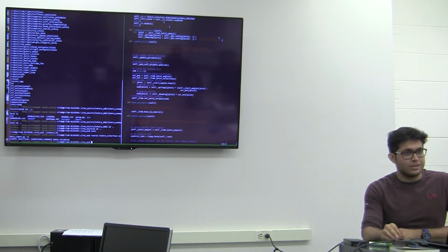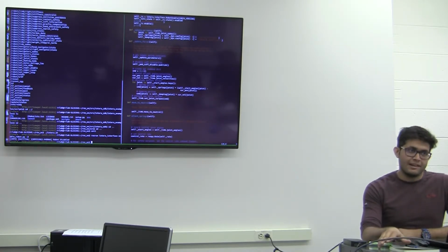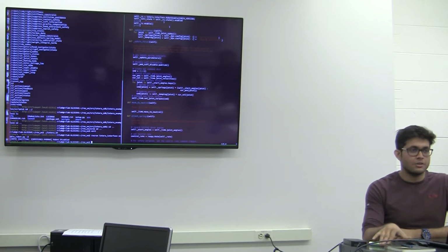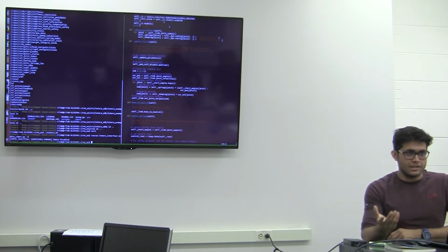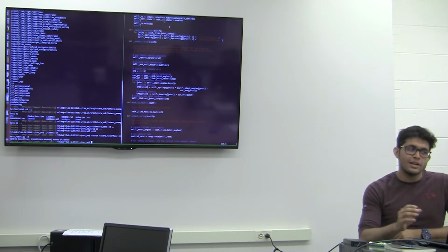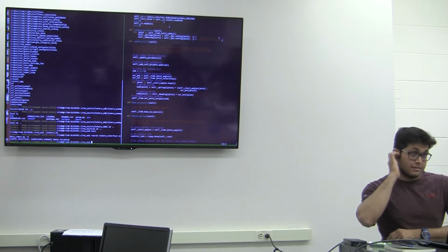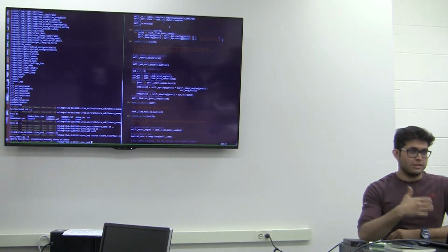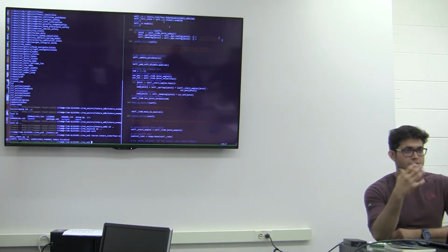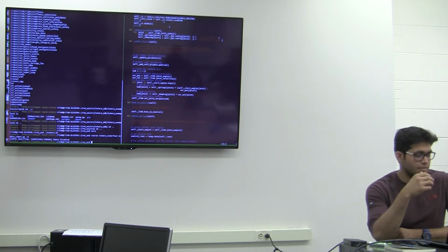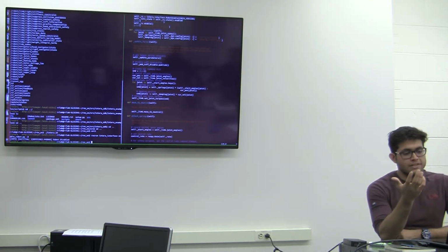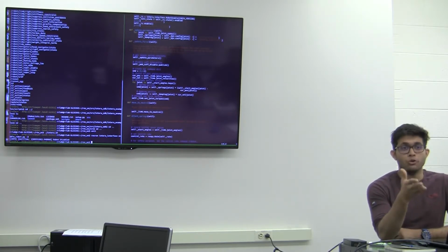Like axis, roll, pitch, yaw of all the joints and stuff. It's very interesting. I like working on URDF. It's very hard though, but it's fun. The Gazebo parameters and all those. URDF is a vast thing. Now they are using macro instead of plain URDF. They have many more features, so you can call things or do math inside those URDF files. It's very fun. If you face any issues in the URDF, let me know, but URDF is usually needed when you have your own robot.